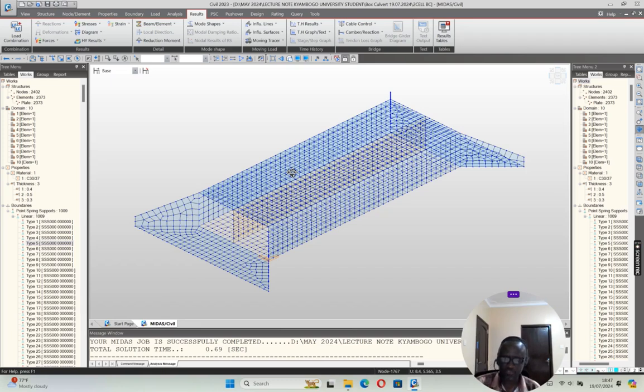So my load application will concentrate more on the external. I am very confident that by enhancing the bearing capacity using the rock fill, or to some extent I would have used rubber concrete with bearing capacity almost between 700 and 1000 kPa. This time I'm using loose rock, well compacted.